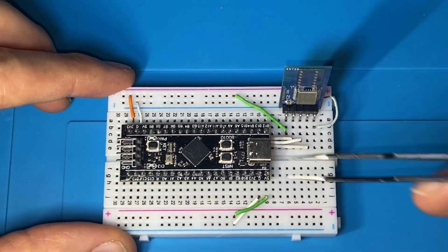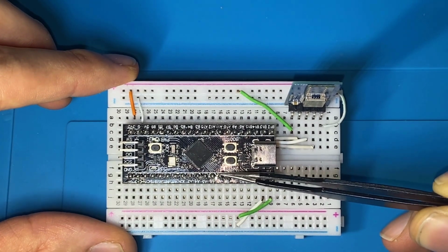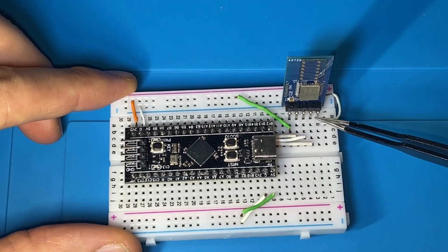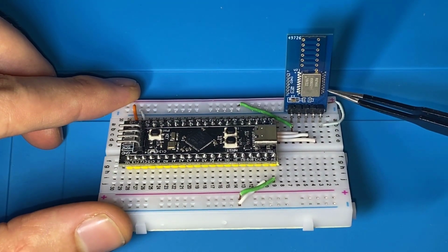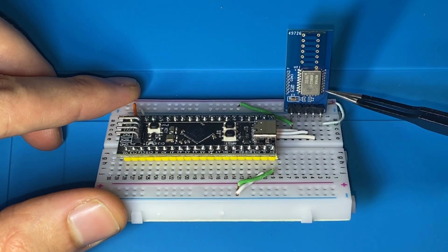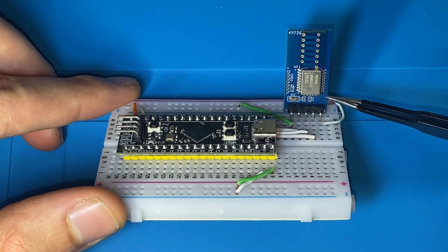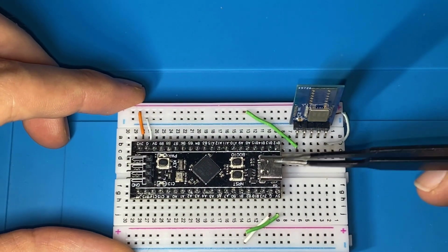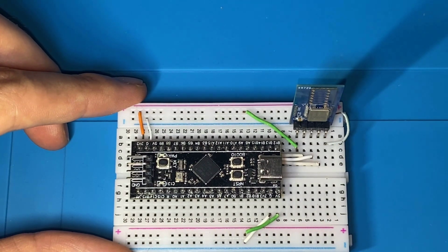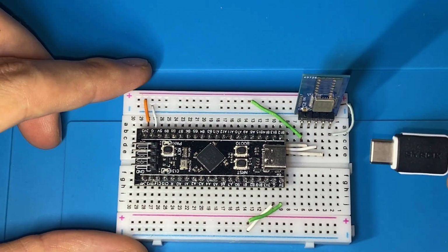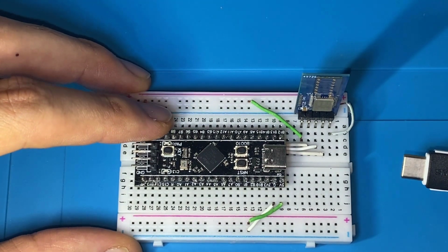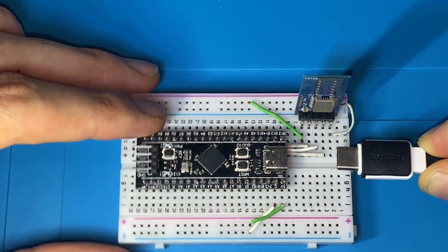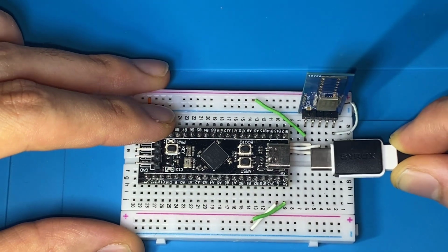Alright, so here's my setup. As you can see here, I have my Black Pill board. It has an STM32F411 and it's connected over UART to this Bluetooth module from Reax, the RYGB211. It supports the 5.1 Bluetooth standard, Bluetooth Classic and Bluetooth Low Energy, of course. And my system will take its energy from the USB connector. I have this USB Type-C connected to my PC, and I have my STM32 configured as USB CDC. So when I plug this into the USB, my computer will see this system as a virtual COM port. So let me plug this in.